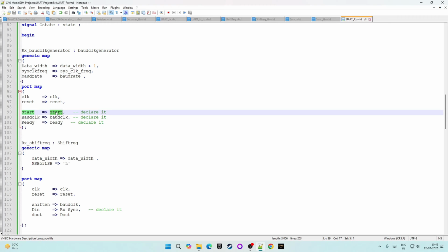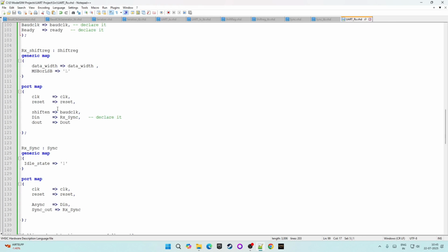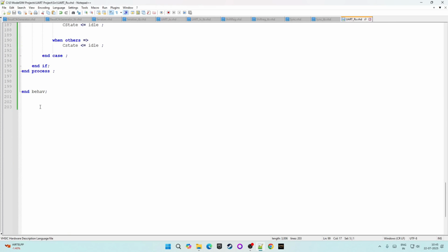So it will be a big synchronization problem. As a good practice, I should expect to receive the data at the middle of 2 successive pulses coming from the transmitter module. That will guarantee that we capture the right data at the right bit. So think of it like this. Suppose this is the clock signal.